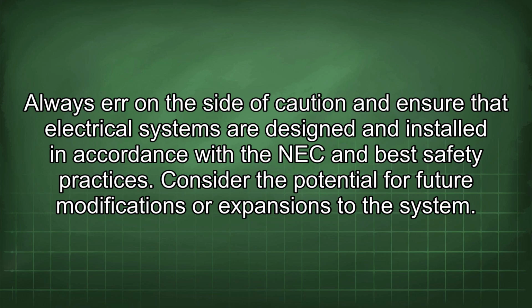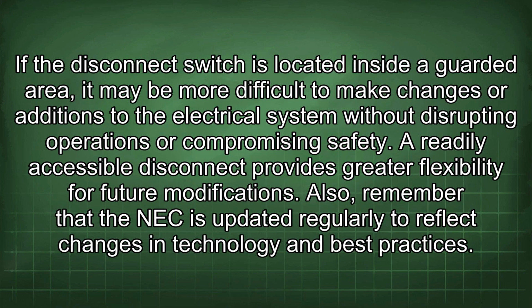Consider the potential for future modifications or expansions to the system. If the disconnect switch is located inside a guarded area, it may be more difficult to make changes or additions to the electrical system without disrupting operations or compromising safety. A readily accessible disconnect provides greater flexibility for future modifications.